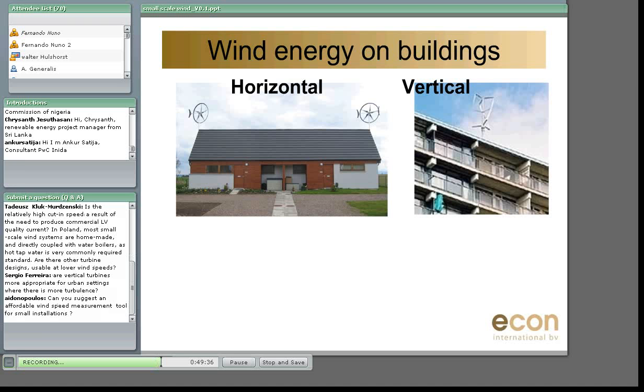If you buy an affordable one, please note the accuracy of the system. As mentioned before, if you have an error of 10%, you will have a deviation of 30% in the power output of the wind turbine. So you should be very careful about what kind of installation you will need, and it depends on what affordable is for you. I would recommend you to hire a system.